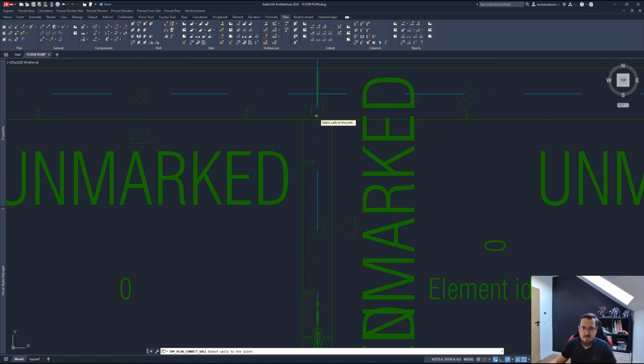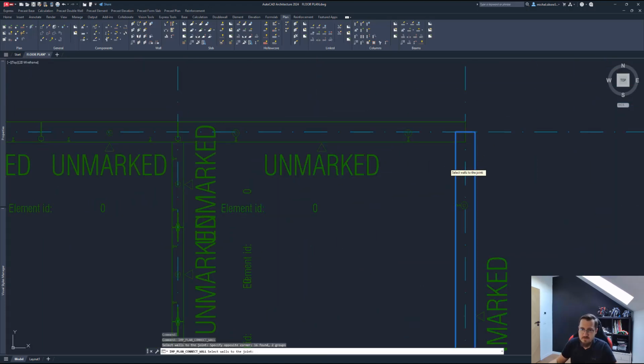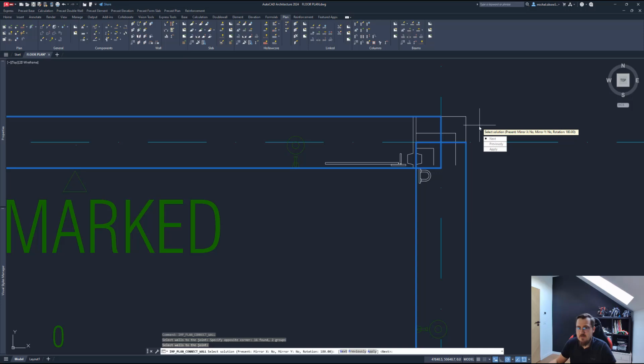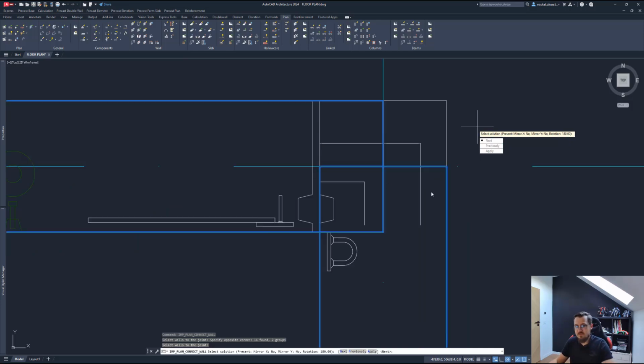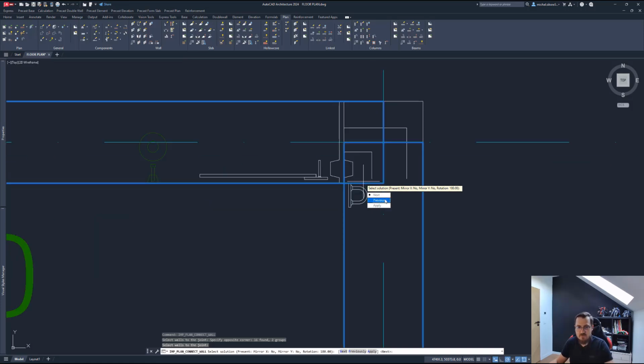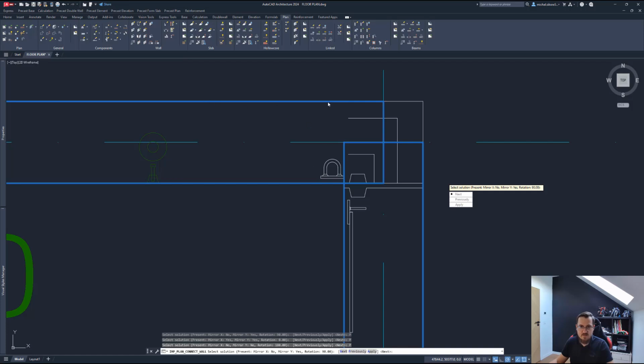So, next, let's actually place this connection. So it will automatically detect that it's a corner connection between sandwich panels. I only have one type of connection like this defined, so this is the only one that it proposes. I don't have a wire loop connection defined for elements like this. So the weld plate connection is only applicable here. And to demonstrate how the preview looks, see, I can specify which element gets extended. In this case, it would be this wall, and this would get shortened, or the other way around.